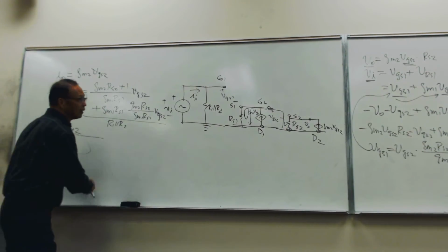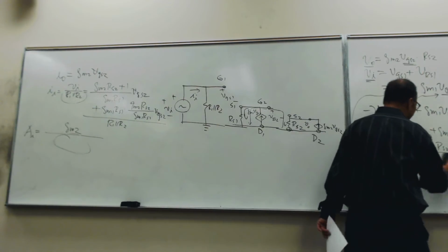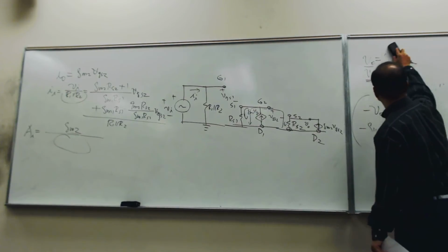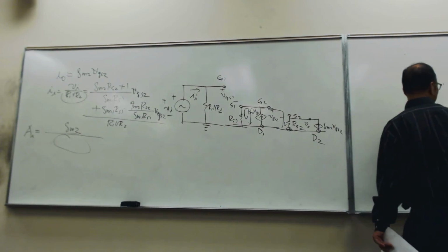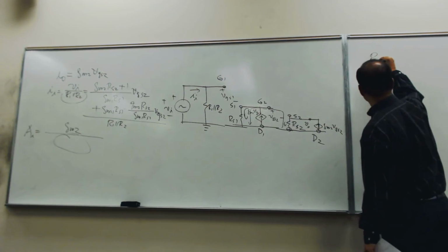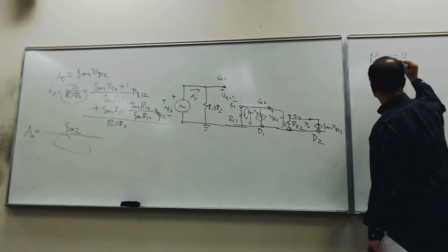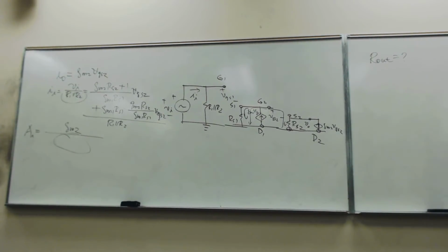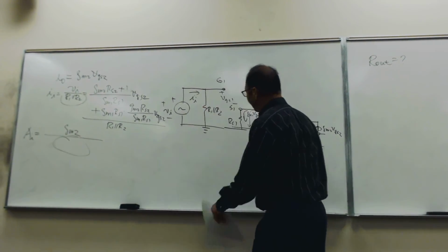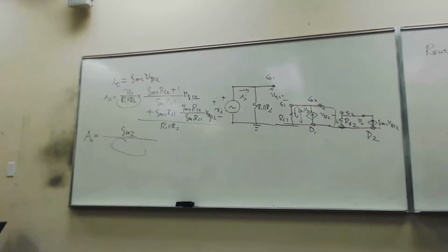All right. So next, let's try to find out what is the output resistance of the amplifier. Okay, so let's try to find out what is R out. Yes? To do that, we have to put a test voltage, yes? And then we would disable the supply, correct?